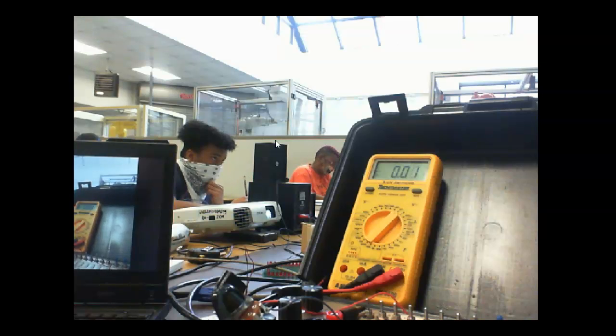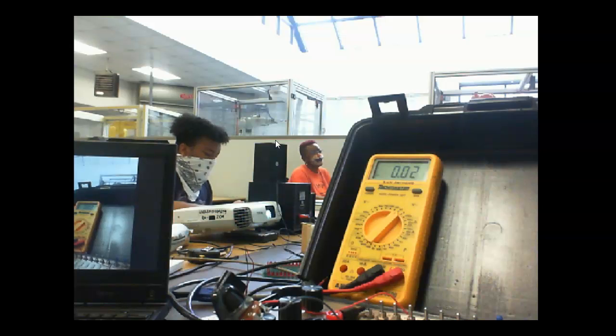Here's the emitter voltage. It's measuring 1.78. If I add 10 plus 1.78, that gives me 11.8 volts, and we're only applying 10 to the circuit. Well, the transistor's cut off, guys. Where's the 1.7 volts? It's because there's no current flow through the PN junction, right? So this wouldn't be added to the 10 volts. But it appears to make Kirchhoff's law invalid. So that's the voltage across the collector. That's VC right there.